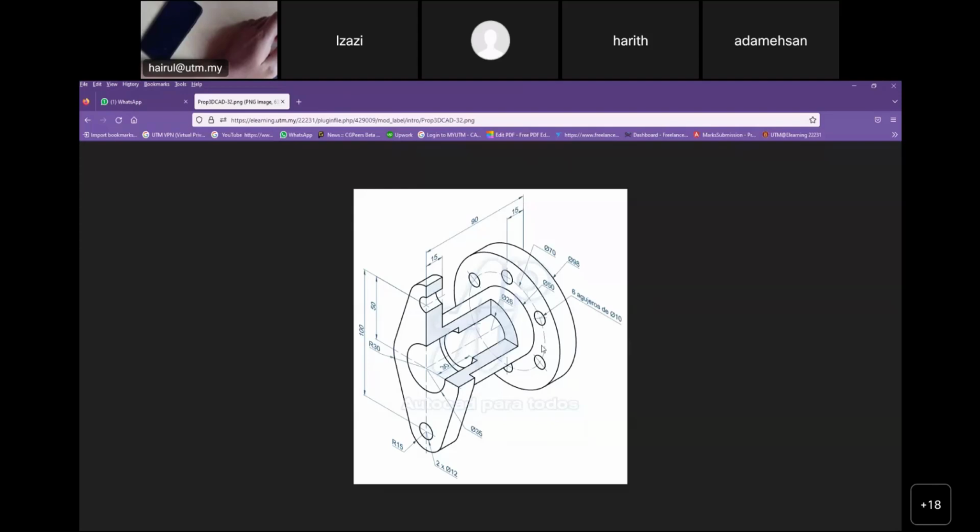You can extrude it to become a hole, then you can repeat the pattern by using, okay, this is a new command for you. We call it circular pattern. Class, are you listening or not? Right, we have 6. Then we have 6 holes. I don't have to cut extrude 6 circles, so I can repeat the pattern.